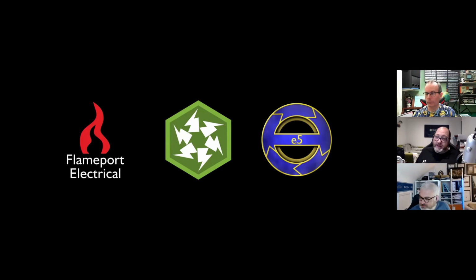Oh, the helixes. Yeah, the helixes are just awful. Pigtails. Can you think of any standard or any criterion that you could refer to that would be detrimental to this? No, I would talk about the bending radius of conductors. Oh Christ, I can't remember where that is now. Hang on. Yeah, this is the thing where you've got your bonding conductor and someone's wrapped it around a broom handle first, haven't they? And stuck it into the terminal.